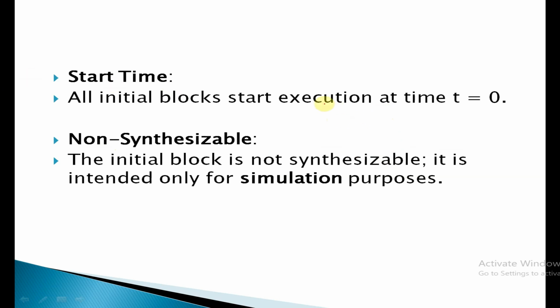And we've also seen this: all initial blocks start execution at time t equal to 0, and this is a very, very important point. Initial blocks are non-synthesizable, and they are only intended for simulation purposes. During the test benches we will see this initial block, and during the design we don't encounter this initial block, so this is also a very, very important point.